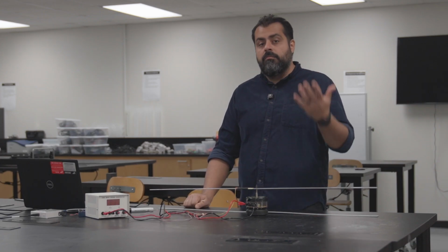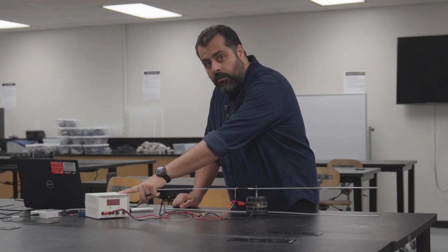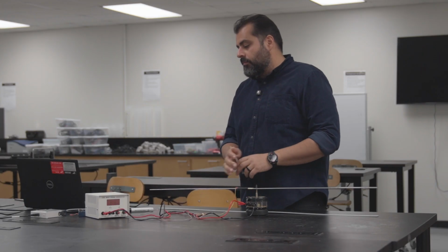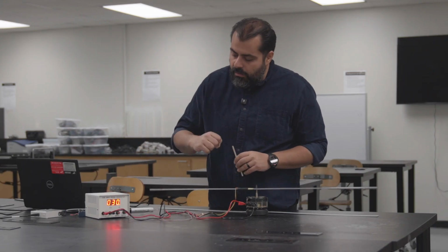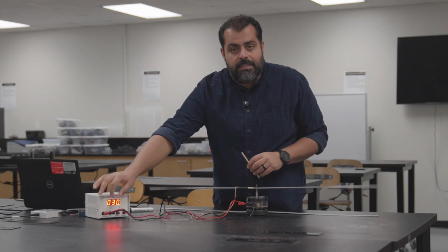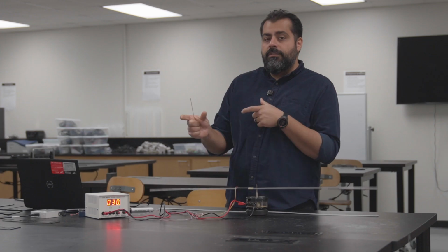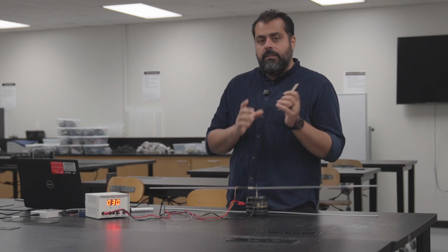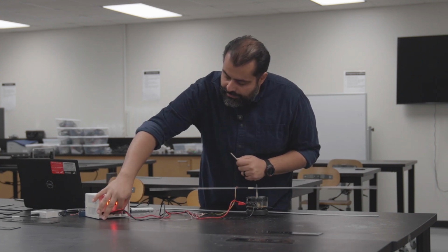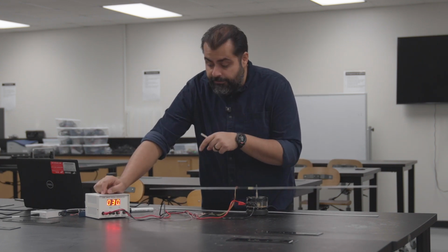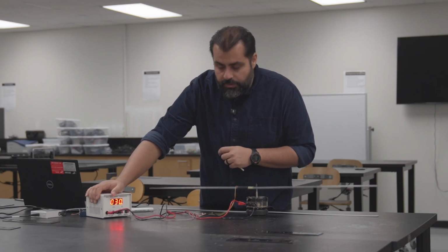Okay, so what should we do? You're given the natural frequencies. We are going to turn on our signal generator. Pretty simple, it has a turn on button at the back. And we are going to change the frequency that is given to the beam. You have the values of natural frequencies for the two different theories, so 6 total values, 3 for the cantilever beam, 3 for the free beam. And you make sure you set the given frequency to those natural frequencies.